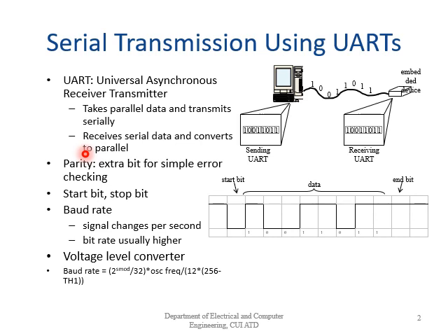We use parity bit for error checking. For example, if we have an even number of ones, we make them odd by adding odd parity. So at the receiving side we can verify that if the number of ones is odd, it means that data is received correctly. If the number of ones has changed to even, it means that there is some error.